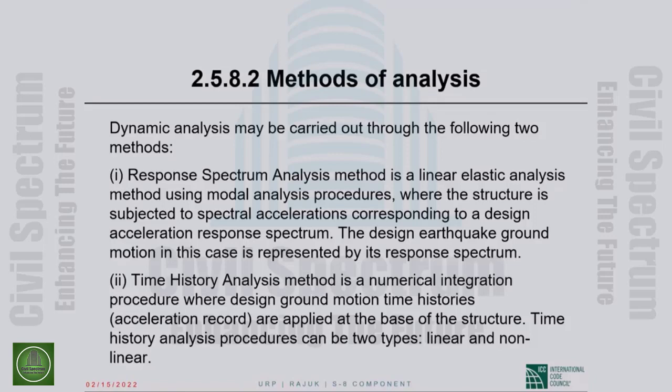The concept is that the structure set in vibration is simultaneously undergoing vibrations in a number of different modes, which means in a number of deformed shapes. So the structure is deforming into a number of deformed shapes simultaneously, and the deformed shape of a structure at any particular instant is the combination of these fundamental shapes that we talked about.